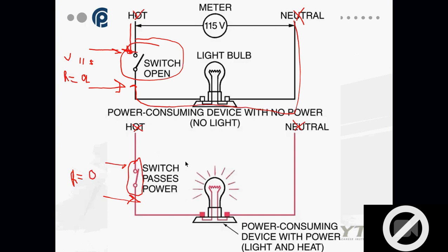Okay. Turn the power back on here, okay? I can't erase my little lines there easily. My voltage from here to here with the circuit drawn as is, what? Some number? Should have none. Should have no voltage. It should be 0 because I have an open switch in the circuit. I'm not going to have any voltage. Again, there's nothing getting down here. There's no hot coming down to the bulb.